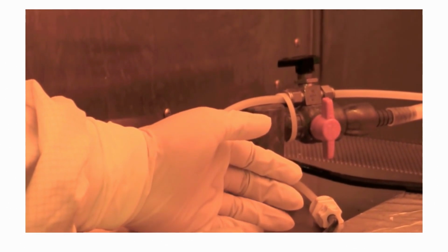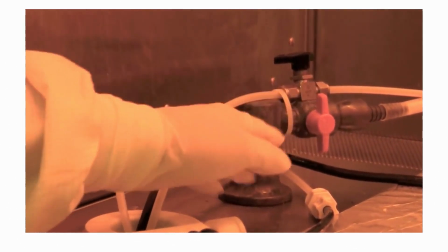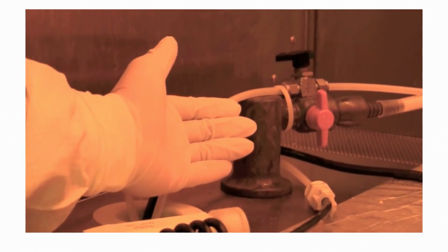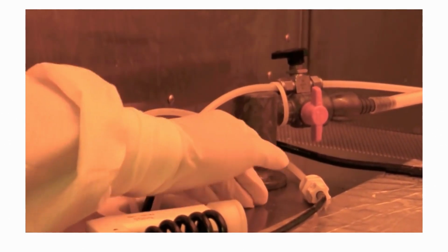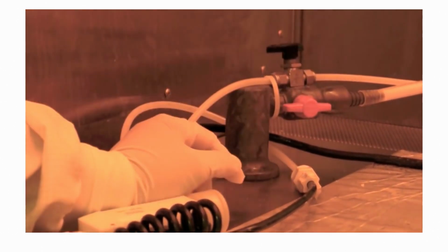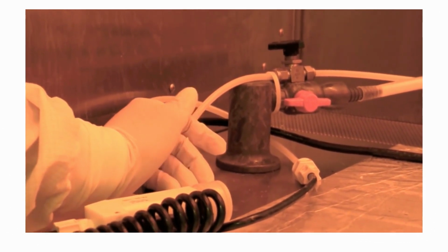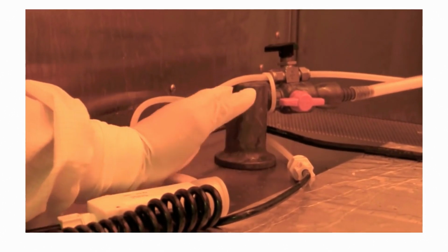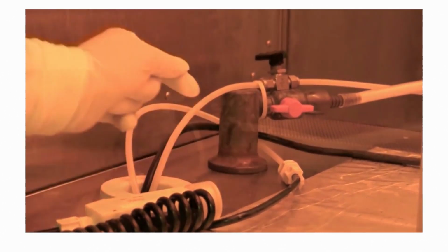This is also why we keep them closed. By keeping them closed when the tool is not in use, we're preventing any kind of buildup from getting into these lines, which will make the lines either harder to open and close or not functional at all. Now the vacuum line is provided by the building. If you ever hear a loud noise opening this line, as you see, there's no loud noise, it'd be pretty obvious. That means there's a problem with our vacuum line. You should report it to staff as soon as possible because this is provided by the building and we have to notify them to make sure that there's no problem upstairs.